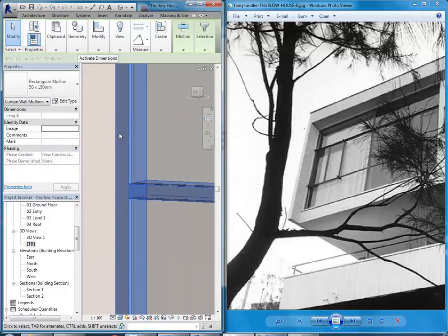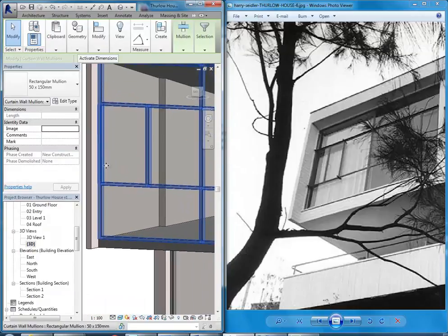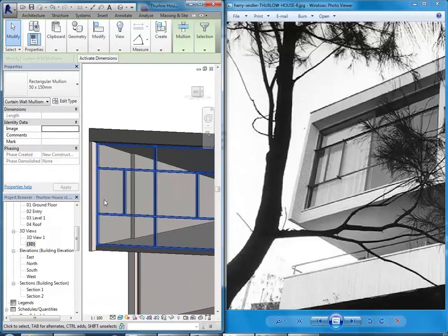So when the mullions are made by the wall, you can have automatically generated mullions, and then you can't manually edit them. Actually, just try and see if you get the pin option, up on the modify panel. Yeah, unpin up here. That one? Yep, there we go. That's fixed it. So see if you've got that one.